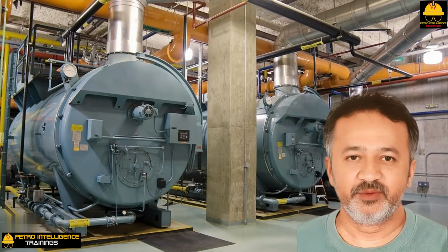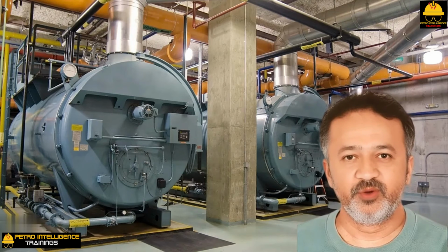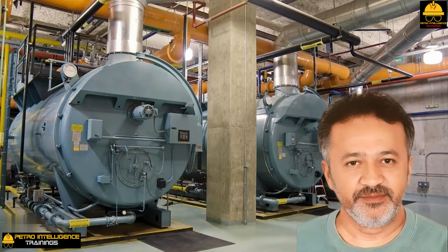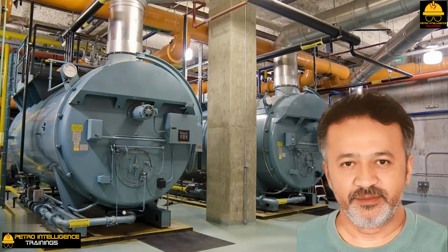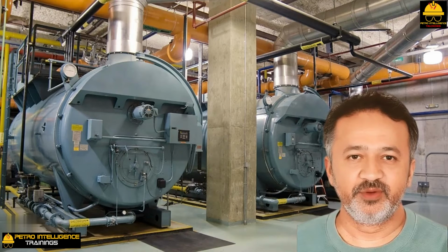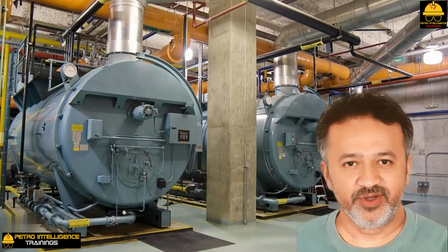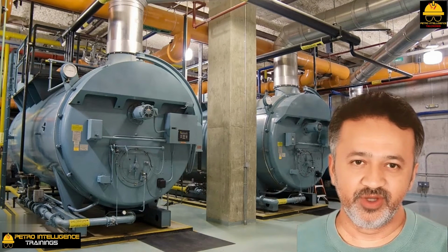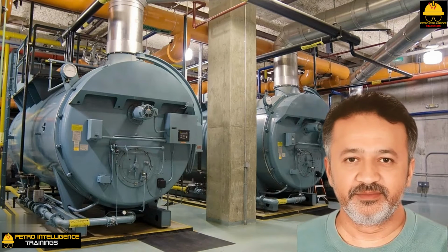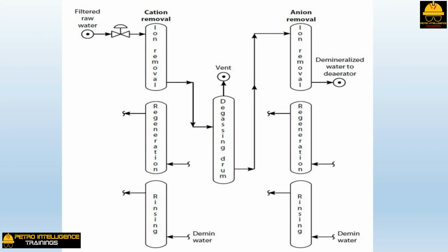Oil settling operations are best carried out below 100 degrees Fahrenheit. Although skimmers and diatomaceous earth precoat filters can operate at higher temperatures, that is 175 degrees F, the temperature limit is usually based on the temperature at which silica dissolves. Incidentally, the typical optimum pH of water in a boiler is close to 9 to retard boiler tube corrosion, shown in the picture.